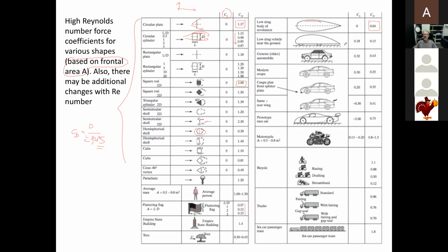All of them had a lift coefficient, which is lifting this way, because the flow comes here and then goes around faster on the top than on the bottom. Therefore, pressure is lower, you get lift. Very, very logical. So you get some lift, and then we get a drag, which is pretty reasonably high.